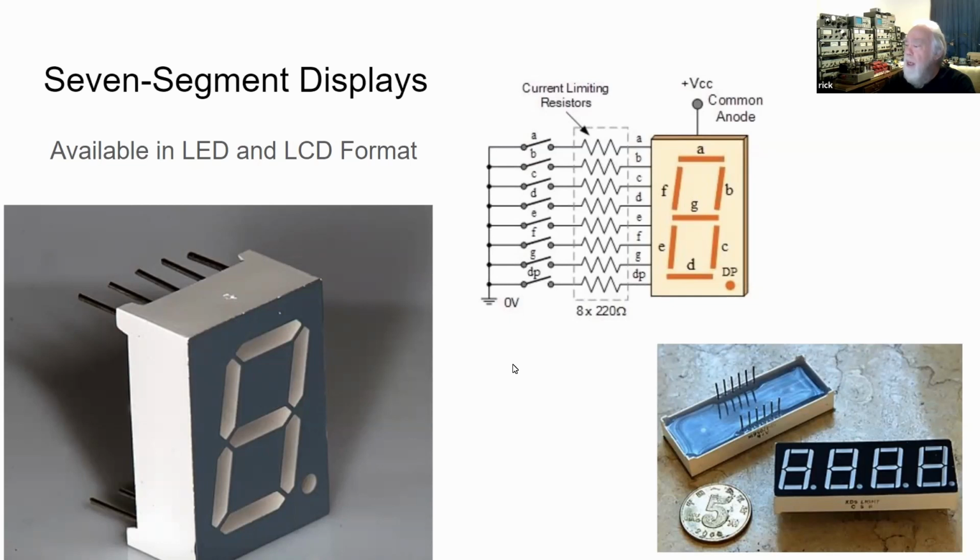But your eye has a persistence of vision and you do not detect the flicker as long as it's greater than 24 changes per second. So it looks to you like the LEDs are on all the time. But if you were to take the clock kit and shake it left and right sideways, then you would be looking at each of the segments as they were changing, and you can actually see the different segments lighting up at different times while you're moving it side to side, because your persistence of vision is interrupted because the target that you're looking at is moving.